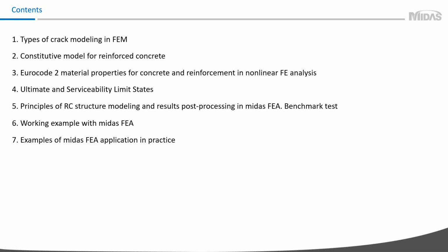On this slide, you can see the contents of what will be discussed today. The purpose of the webinar is to give you main recommendations about how to define nonlinear properties for concrete and reinforcement, how to create a finite element model correctly, how to perform iterative analysis, and how to read and understand results obtained from analysis.